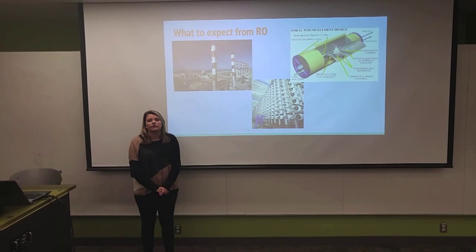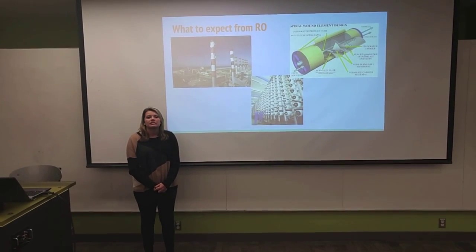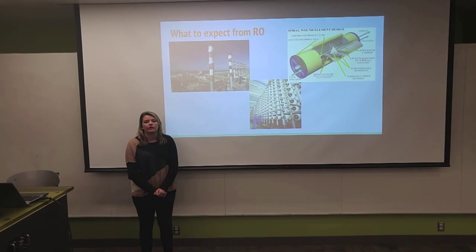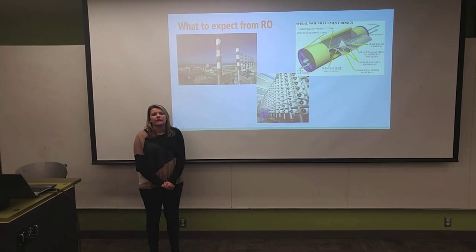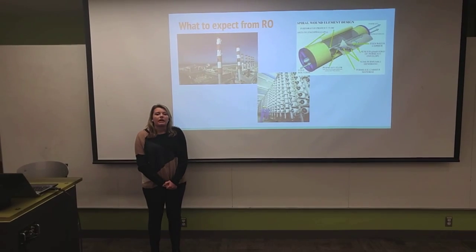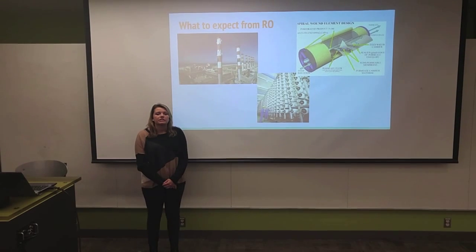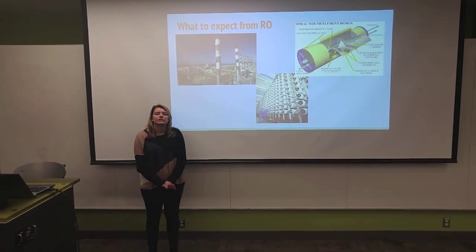Ultrafiltration reduces the use of chemicals and biofouling, but requires a lot more maintenance and at higher costs. Membranes need to have longer lifespans with greater durability, while minimizing the use of chemicals and waste and lessening the impact on the environment, all while keeping costs down. RO is a better method for desalination, and with projected improvements, RO can become an institution around the world and be a solution to the desperate need for fresh water.